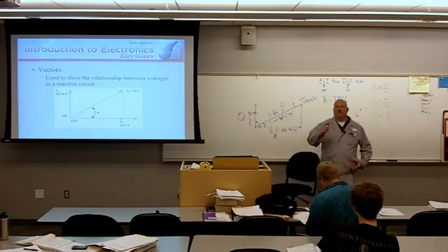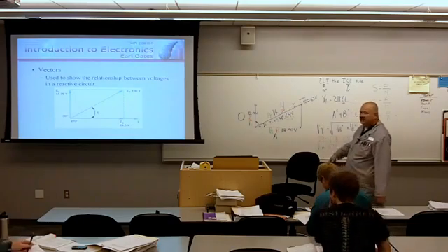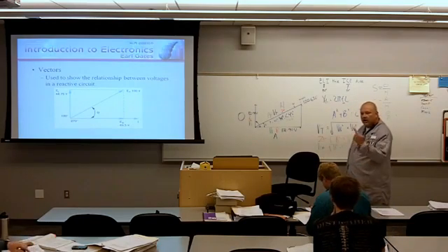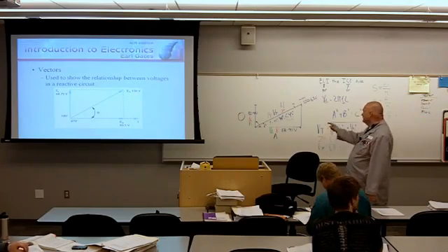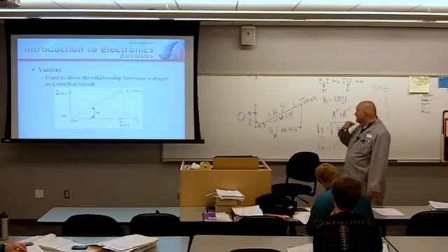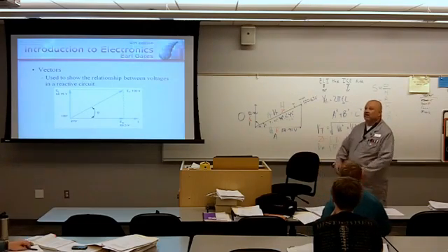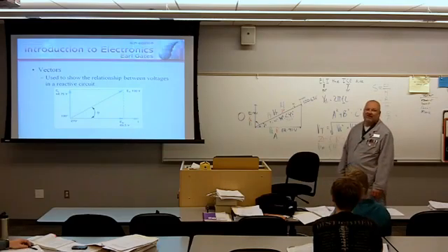So if you told me, by this illustration, there's so much that I could tell. By just looking at this, I could tell this is a series RL circuit. I could tell that this is predominantly a resistive circuit, but it has some reactive components. Seeing that angle theta is 26.6 degrees tells me that it's predominantly resistive and not reactive.